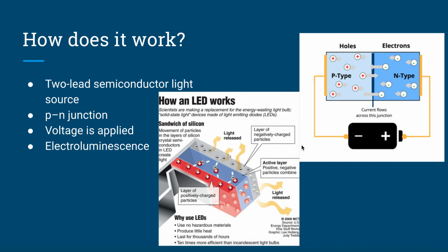A light-emitting diode is a two-lead semiconductor light source. It is a P and N junction diode that emits light when activated. When a suitable voltage is applied to the leads, electrons are able to recombine with electron holes within the device, releasing energy in the form of photons. This effect is called electroluminescence, and the color of light corresponding to the energy of the photon is determined by the energy band gap of the semiconductor.